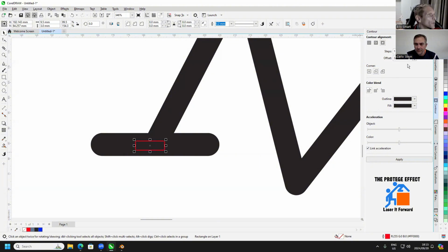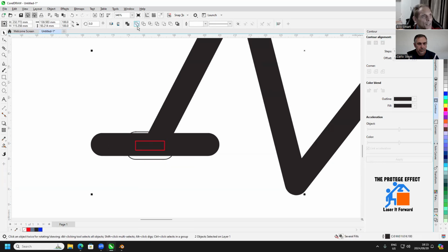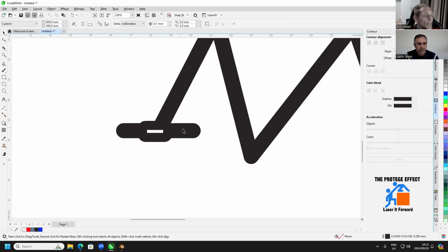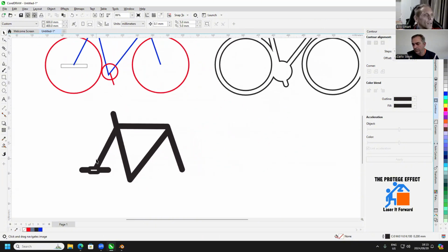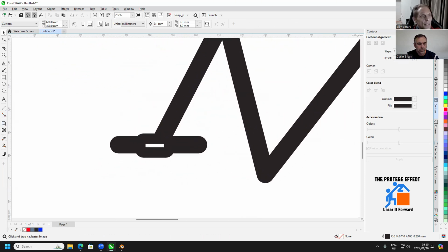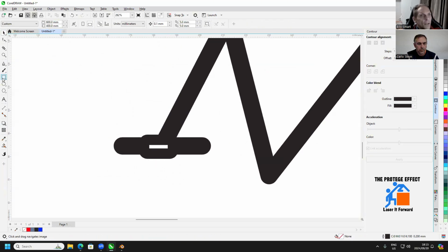So we're just going to do a contour on this 3 mil. It's one of the rules I have, that I never leave smaller than a 3 mil gap anywhere on my sides or onto anything. It just becomes too finicky and might eventually break. So there I just cheated it and I just made it a bit fatter so that there's some strength in there. I'm not saying this is going to be elegant. It'll certainly be functional. All right, so over there, I've made, was that a 10 mil, 9.5 mil. Yeah. So over there, I've made a 9.5 millimeter.